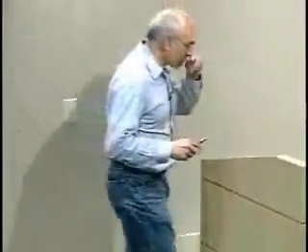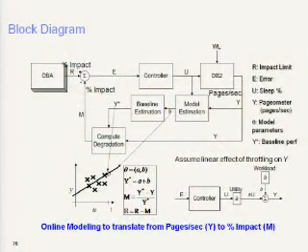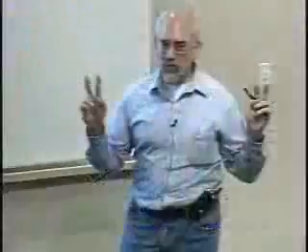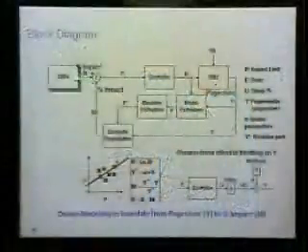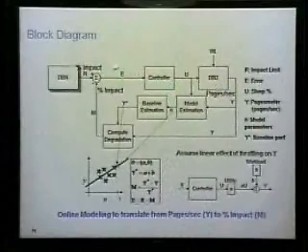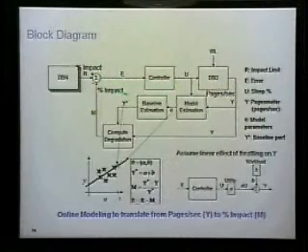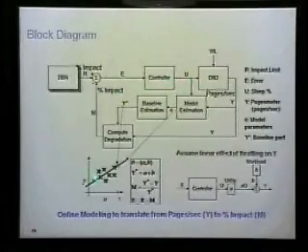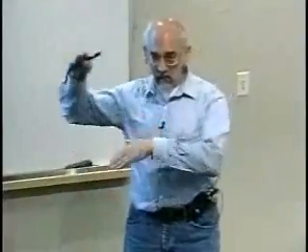Now, let me point out something, because there's a subtlety here which may not be altogether apparent, and this is inherent in any sort of adaptive control. I use this word, persistent excitation. Let me tell you what that means here. Suppose my control is really, really good, and so I essentially have a zero error term over here, and I'm keeping this at a fixed setting. Well, I'm not going to be able to figure out a curve like this because everything is right in there. And that's why you see some of those bumps up and down. You want to vary U a bit, because if you don't, you can't get a reliable line.